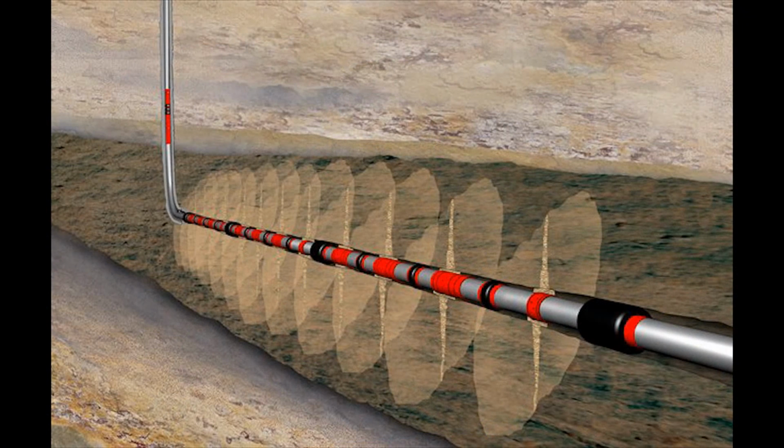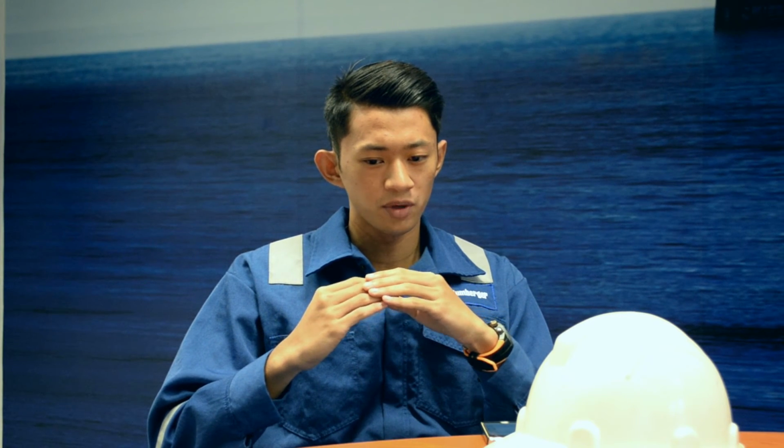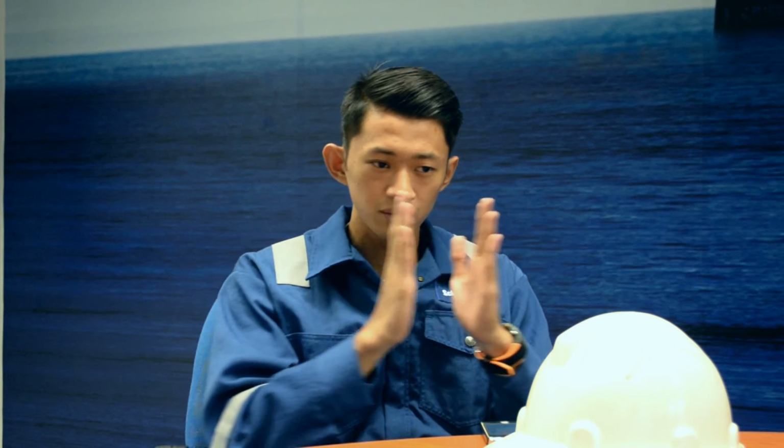Now the third one is the perforation of the well. Most oil companies have been reluctant to cement and perforate the entire length of the horizontal well. But in well testing, we actually need just a little perforation. We don't need much. So they need to reduce their perforation intervals to just a few small ones between them. A large perforation can actually become a difficulty for horizontal well testing.